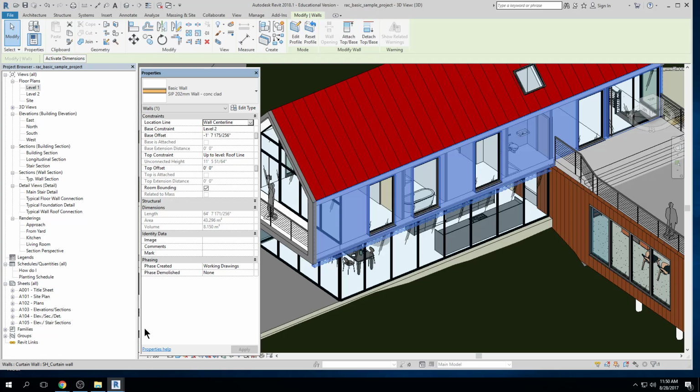In Revit, we phase items, and we get kind of that same visual gradation, but things turn on and off depending on what phase you're in, right? So if I'm in the existing phase, I may see the existing shell and the elements to be demoed. If I'm in the new phase, I'll see the existing elements, but the demo stuff turns off and the new stuff turns on, right? So phasing allows me to sequence my drawings so that they make sense, okay?